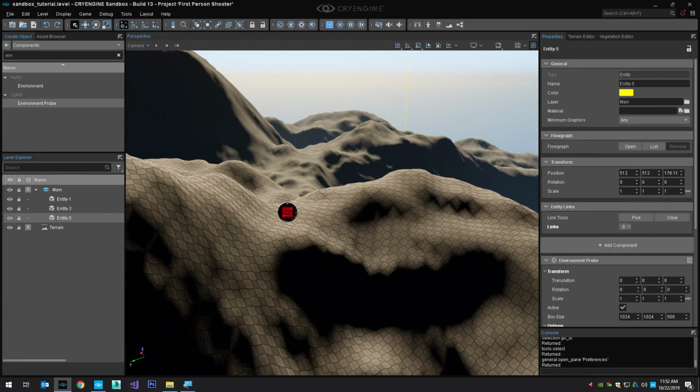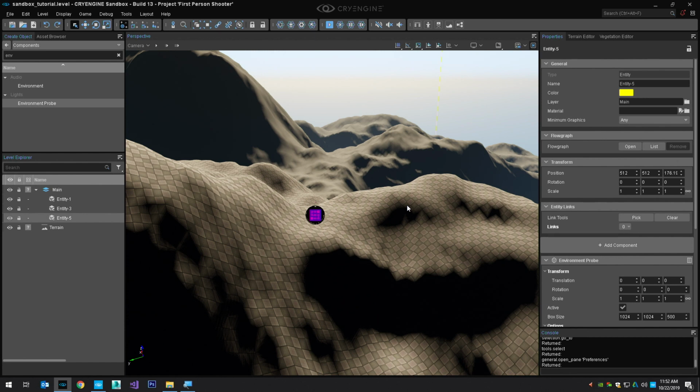OK, so I've positioned this thing dead center, and now I actually need to generate what are called cube maps. If you pretend I have a cube, and it has 6 pictures, top, bottom, front, center, left, right. And so it says, what does the world look like over here? What's the world look like above me, below me, this way, and that way? It literally takes 6 pictures. And then it reflects those on this sphere. And so all the objects then use this map of what the world looks like, and it creates correct reflections. This is a baked map.